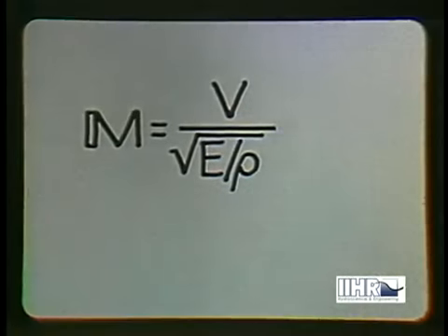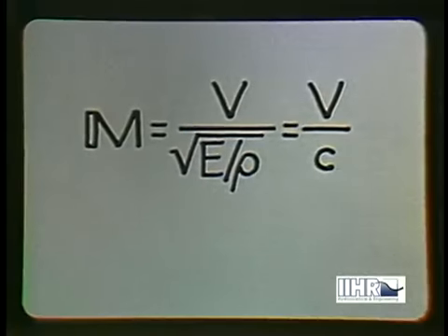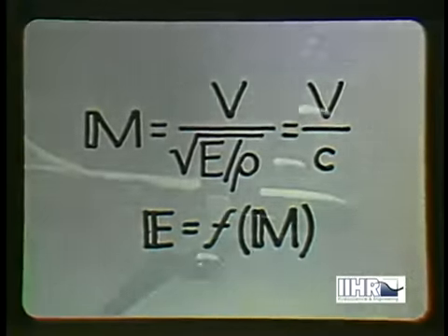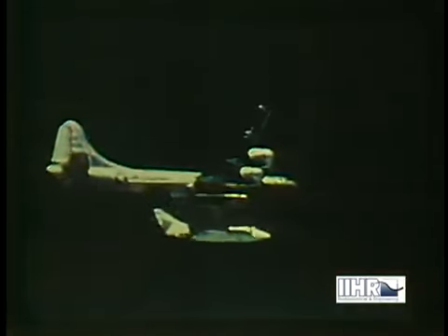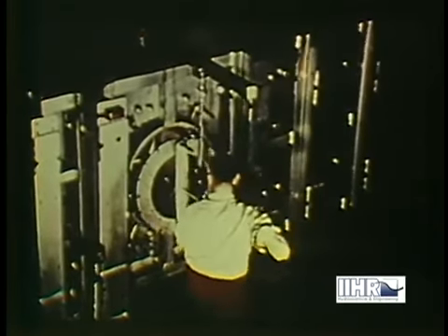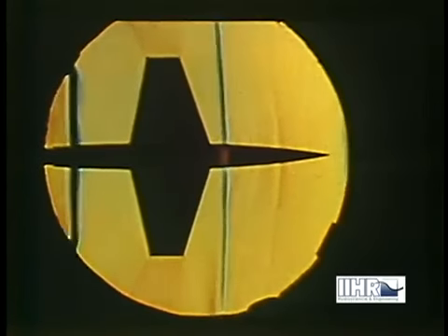If it is the fluid elasticity that is important, the essential ratio takes the form of a Mach number, the denominator of which, it should be noted, is the speed of sound. The Mach number now controls both the Euler number and the condition of similarity. Flow in which the elasticity or compressibility is a factor is well represented by today's supersonic planes, such as this NASA experimental craft. In a supersonic wind tunnel of the NASA at Langley Field, the sound waves which these planes produce and which retard their flight as water waves retard a ship are observed by the Schlieren process as the Mach number rises.